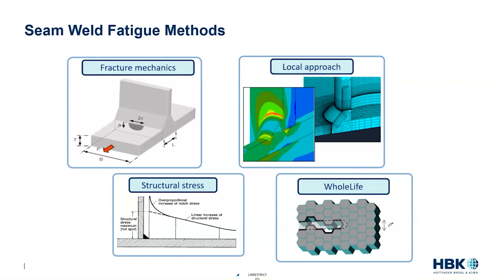In terms of breakout models, they are much more efficient, but typically the ones I've seen have all been very much plane strain. Think of like a cross-section cut through the weld and looking at the weld in 2D. It's very powerful if I have a continuous weld, but typically where we see weld issues is at weld terminations, and these don't really handle that all that well.